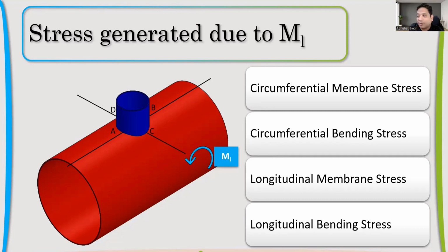At all the points which we are trying to calculate, there is stress already existing. Forget about secondary, Himanshu. PM is actually primary stress. Even if there is no local load, this nozzle load is not there, still that PM is there. Why? From where is that stress coming on all the points? Internal pressure, absolutely right. So that is already there, and you know that in the circumferential direction, it is twice that of the longitudinal.